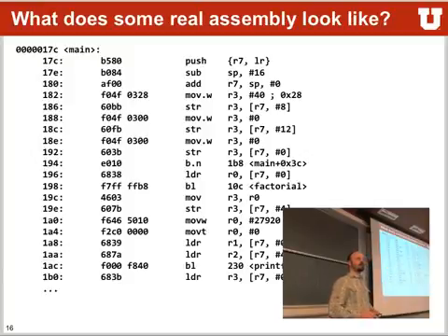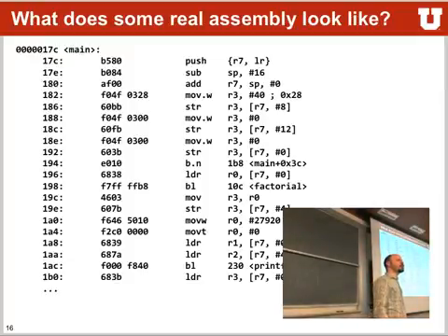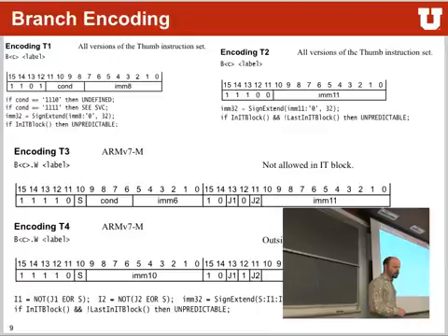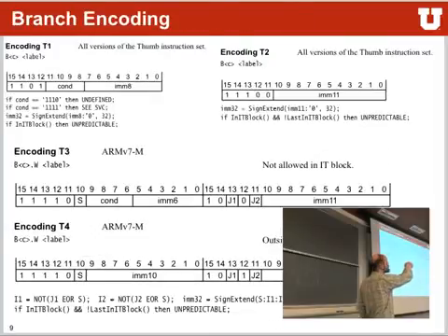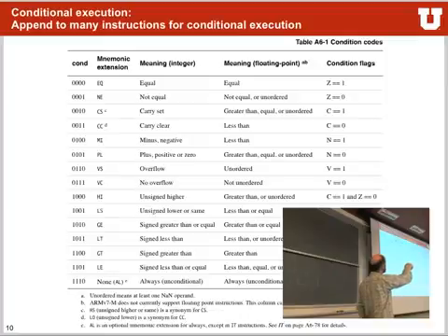Does the assembly guide have the actual register values? Is there a map from the logics to the actual register values? Yes, there is. Here, conditional, that's the encoding. So if you look at, for example, if you want an EQ, the condition would be 0000, or an NE would be 0001. The conditional is stored in this instruction. So if it would be a 1101 and then 0000, and an immediate, it would be a branch equal instruction.